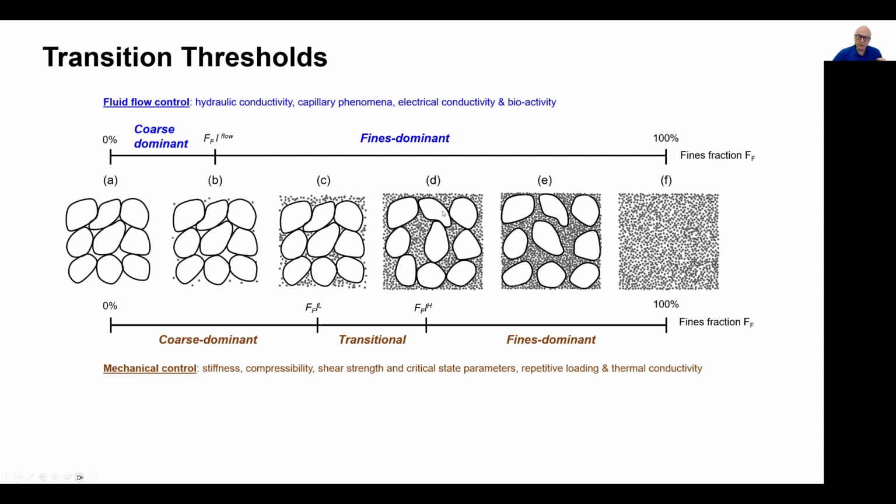Now, as we add more and more fines, eventually the gravel particles start to float in a sand matrix, and therefore, at this point E, both hydraulic and mechanical properties are controlled by the fine fraction, in this case, the sand.